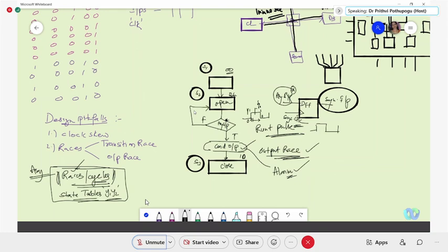Each state variable will be fed to one flip-flop. Each variable will be taken through one flip-flop, as we have seen in our ASM synthesis. So if the next state value depends upon the exact timing of the change of the flip-flop inputs, the order of changing of these flip-flop values, that is called a transition race.